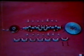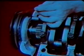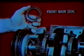We can conclude the crankshaft story now by identifying the parts installed with the crankshaft and its bearings on the engine. At the front of the engine, the vibration damper assembly includes a V-groove pulley. This pulley turns with the crankshaft to drive the engine's fan belt and other accessory belts. The front main oil seal and rear main oil seal fit around the crankshaft to prevent leakage from the ends of the crankcase.